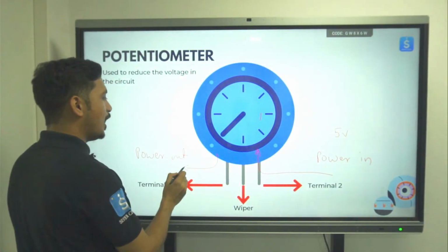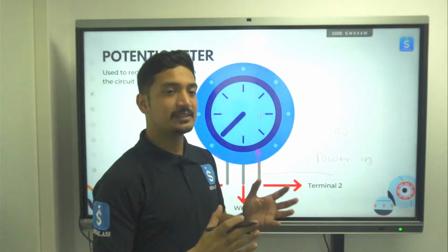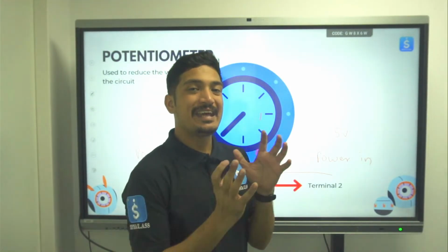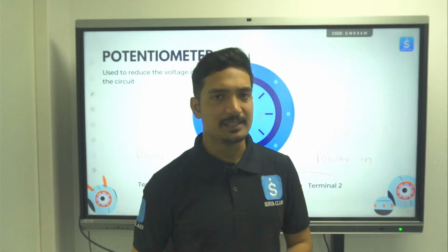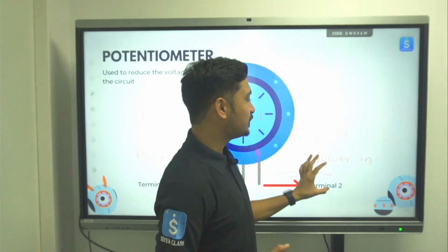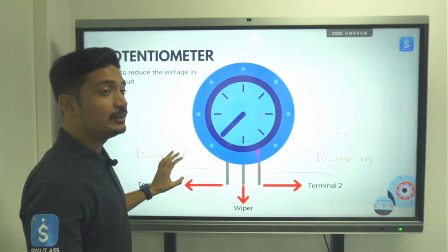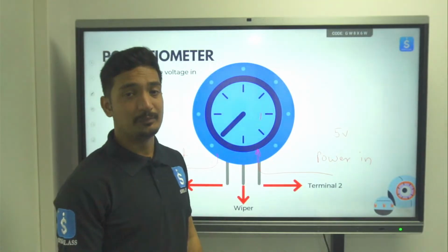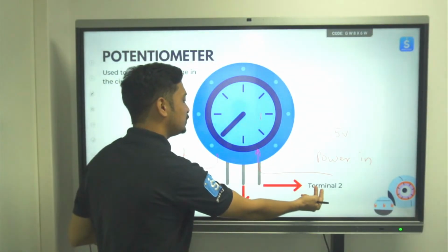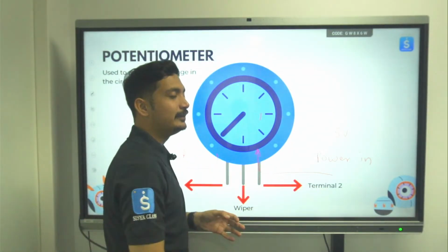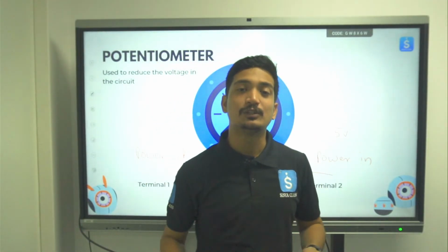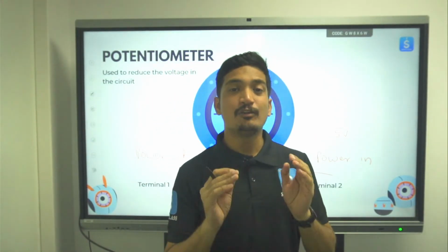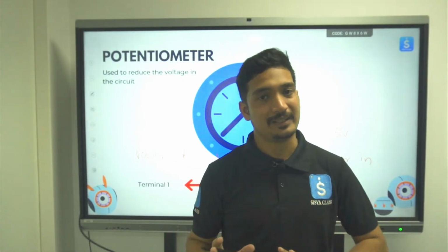To complete the circuit, we connect the negative terminal to the ground pin of the Arduino board, isn't it? Right? Because this is the positive terminal, this will eventually become the negative terminal. The names of these two terminals are just terminal, not anode or cathode, which means we can switch their places, but we should understand the direction of current flow.